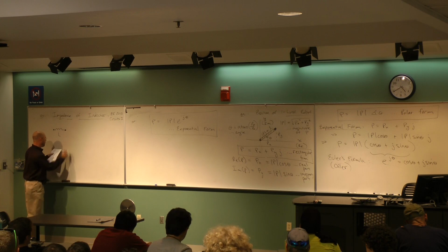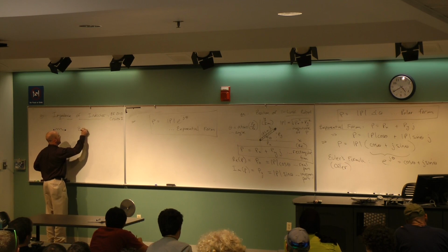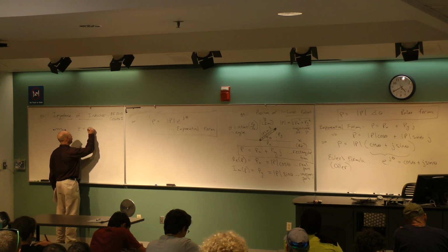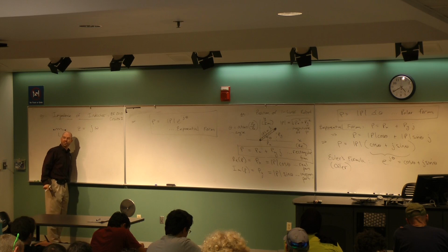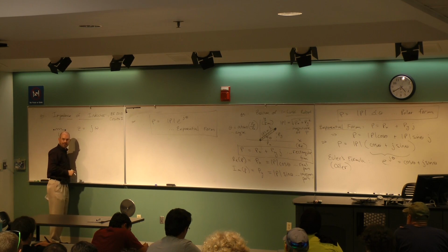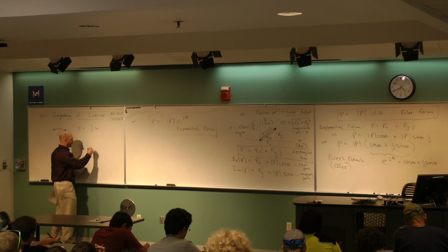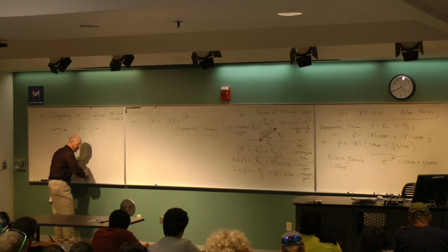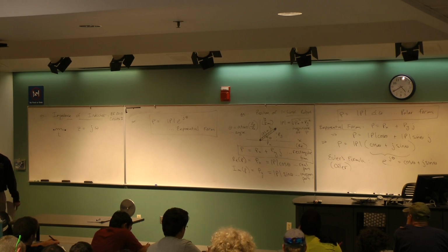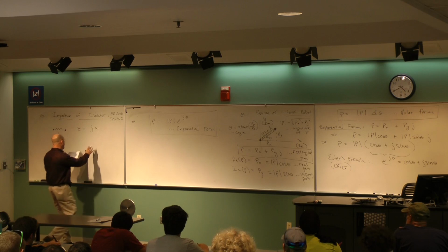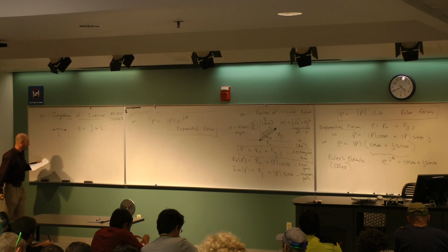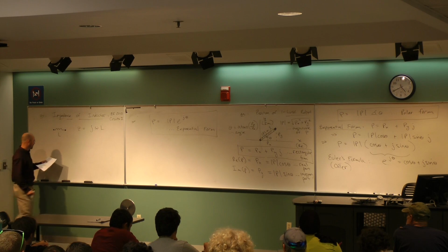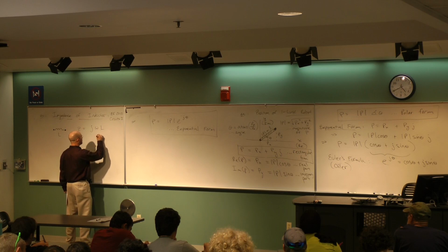So L is the inductance, the impedance is Z. And the way we keep track of this in an alternating circuit is we use j times the frequency omega. This is not a w. This is the Greek letter omega, the one that looks like ohms, but lowercase. It's the frequency, like in a sinusoid, sine omega t, cosine omega t. That's what that is. j omega times L. So that's it. By definition, Z is an imaginary number. j omega L. And so Z is the impedance.